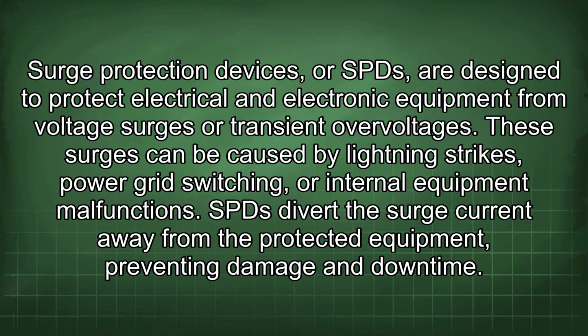Surge protection devices, or SPDs, are designed to protect electrical and electronic equipment from voltage surges or transient overvoltages. These surges can be caused by lightning strikes, power grid switching, or internal equipment malfunctions. SPDs divert the surge current away from the protected equipment, preventing damage and downtime.